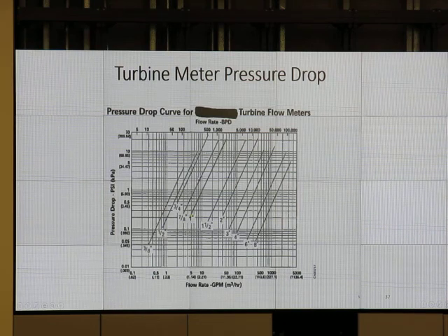So let's look at 500 barrels a day. This is a 1-inch meter. Along the top, we've got barrels per day rate. Along this side is PSI on a logarithmic scale. At 500 barrels a day, if we come down and we cross the 1-inch line, it's right about there, that highlighted line. Come on, 500, 1 inch right there. And we read over, and how many PSI pressure drop is that? 1 PSI. And they had 2,300 back on the injection pump at the station. So that little 1-inch meter isn't hurting them at all.